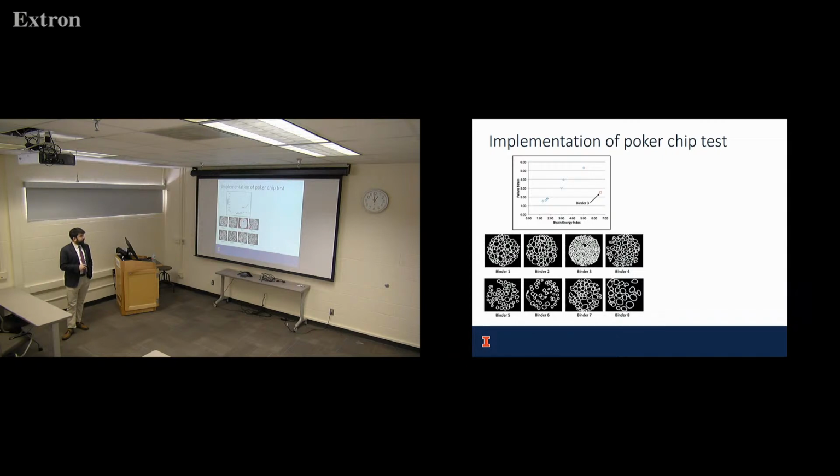Combined with that cavitation, we said, hey, this poker chip test could be a good identifier for those kinds of unsavory additives. And again, this is super important in Texas because you're allowed to modify your binder with anything you want. We're not limited to polymer there. You can actually modify with any modifier. So we knew that there's some modifier that is maybe leading to a really bad result in strength, but they're able to pass it through the PG system still. So this test was really successful.